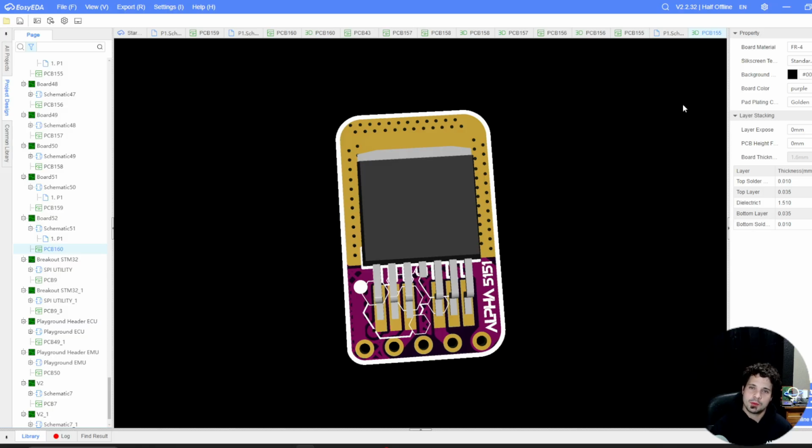Now, traditionally, what we do when an ECU doesn't have the VTEC components in it is we use an external relay. And the reason I want to touch base on this is because an external relay will help you to understand what the internal components on a VTEC ECU are doing. With an external relay, you hook one pin up to your battery, you hook one pin up to your battery's ground, or the negative side. You have one pin that is hooked up directly to the VTEC solenoid, and then you have one pin that's used as a control signal.